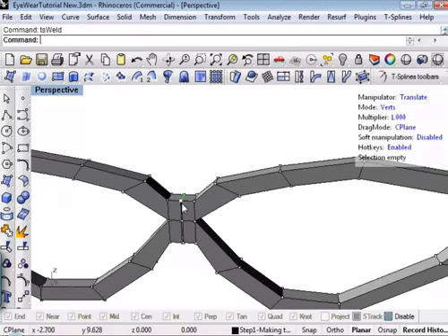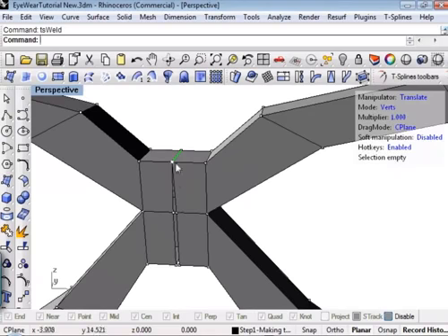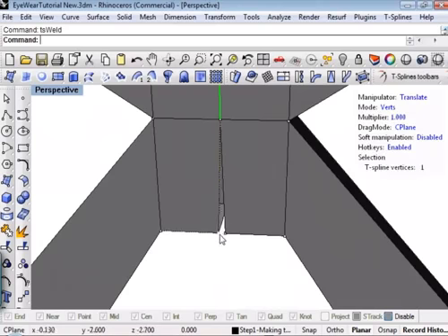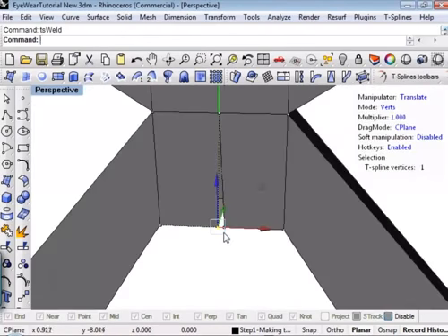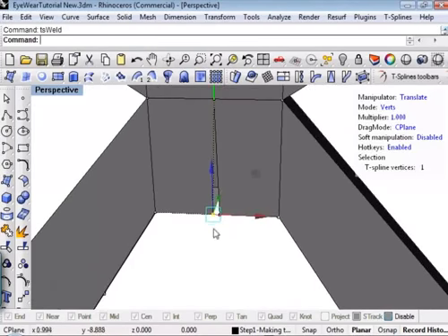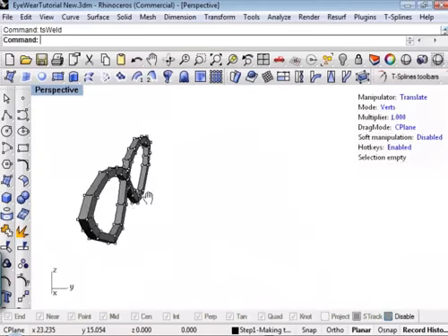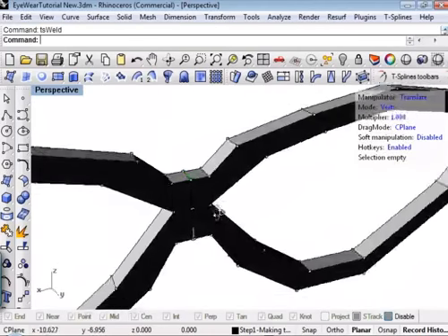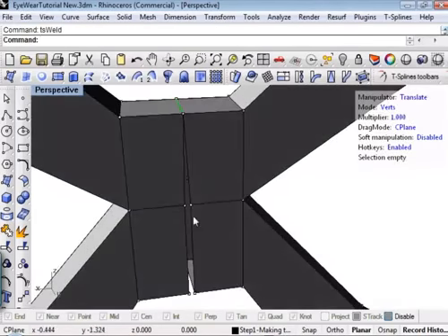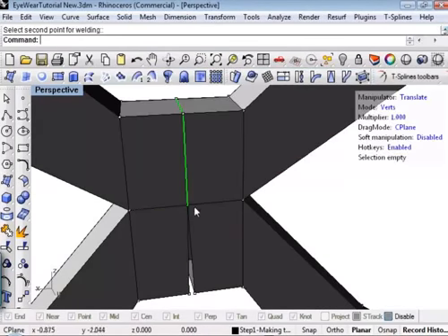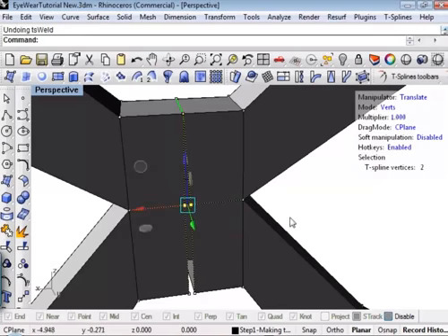you'll notice that my green symmetry line has appeared, meaning that this is now a valid axis of symmetry. So I'm going to weld that one up. Weld that one up. Now I'm pre-selecting these verts, and the reason I'm doing that is if I pick one, hit the weld button, and then pick the other, the first one jumps to the second one.